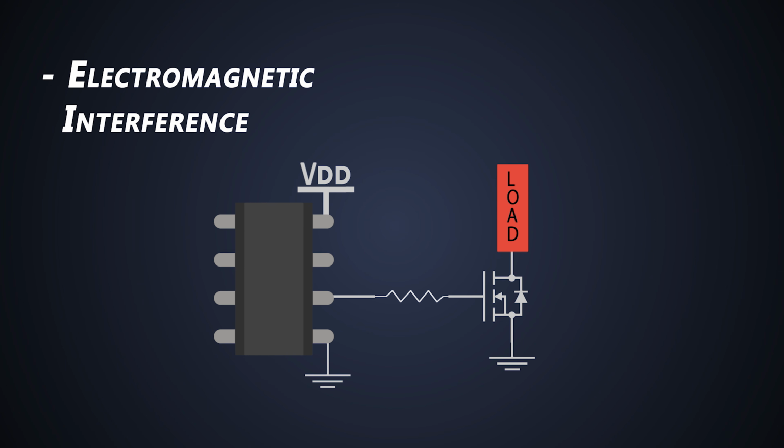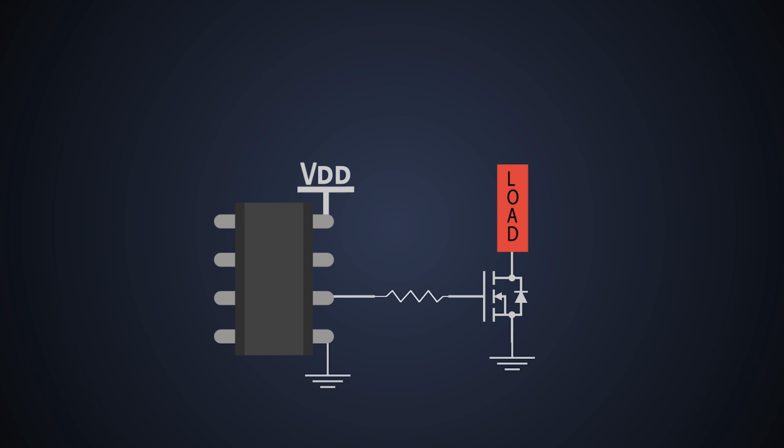When a low gate resistance is applied, the switching will become faster, which can reduce the switching loss. But the noise induced by di/dt and dV/dt will increase with switching speed. So the EMI of the switching device will increase with decrease in gate resistor value. Gate resistor dissipates power in the gate loop and prevents gate ringing.